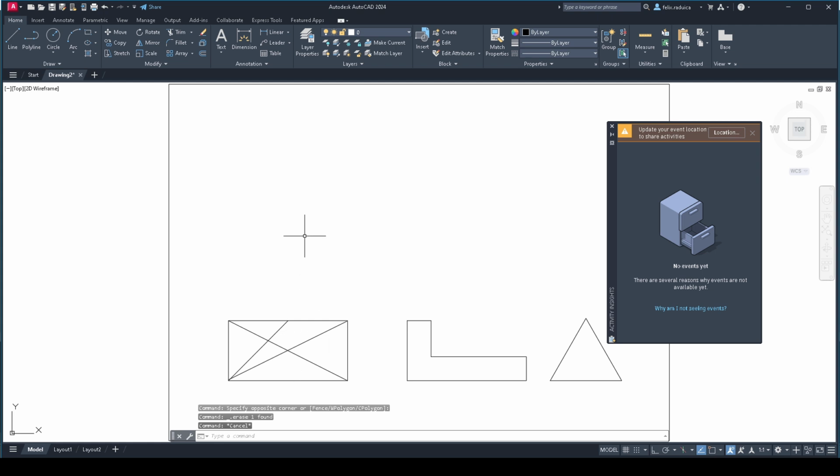Let's draw a rectangle. Give the rectangle command. Click to choose a random point. If you want it to be precise, you can give the coordinates. And then type in the add symbol 50, 50. And actually it was like a square now. It's a square. And that is how you can create a square, or if you want an actual rectangle, you can give different coordinates to the second point so that it is longer or taller.